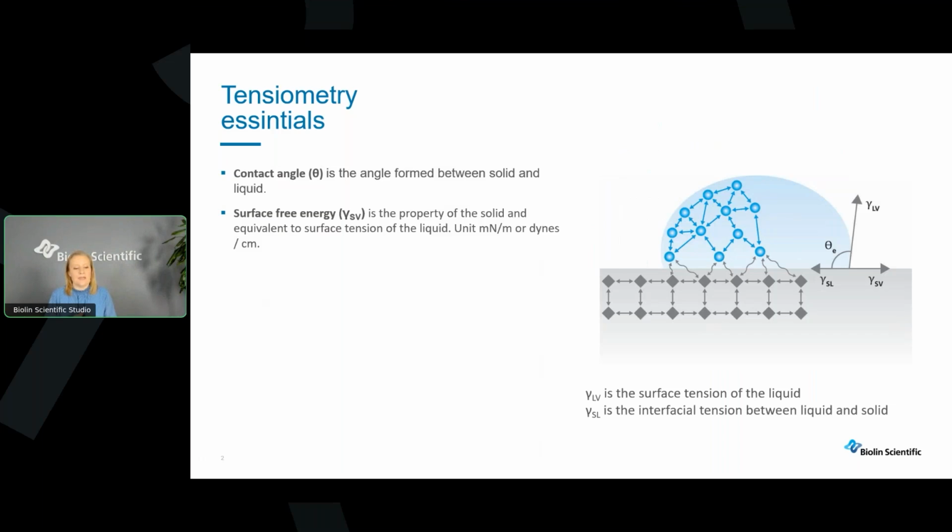So as Henny said, we can measure a contact angle of a liquid on a solid surface, and when we talk about surface-free energy measurements, we typically do this with an optical method. So there are other methods to measure contact angles, but for surface-free energy calculations, you most typically want to use the static contact angle. So that's why we use the optical tensiometer to measure that.